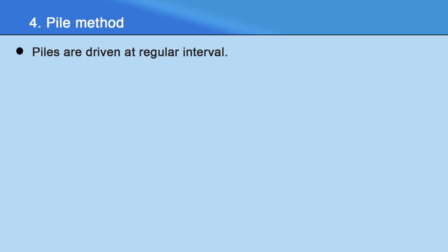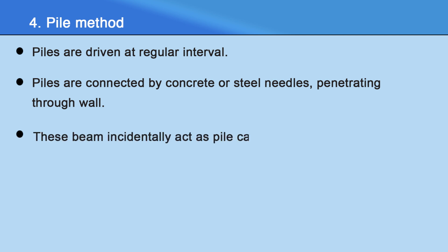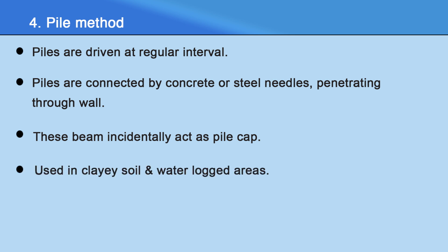Piles are driven at regular intervals. The piles are connected by concrete or steel needles penetrating through the walls. These beams incidentally act as pile caps. In clay soil and waterlogged soil areas, we can use this method.